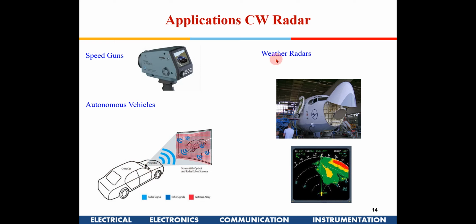On the aircrafts, other than for Doppler navigation, we also have weather radars which operate on the Doppler frequency. Those radars work because of the Doppler shift induced by the clouds and the storm, which depends on how thick the cloud is and how many water particles are there.